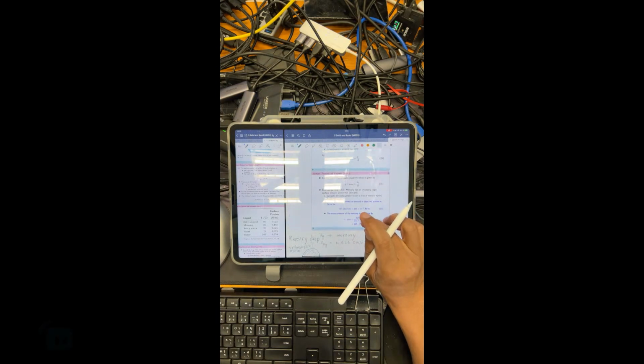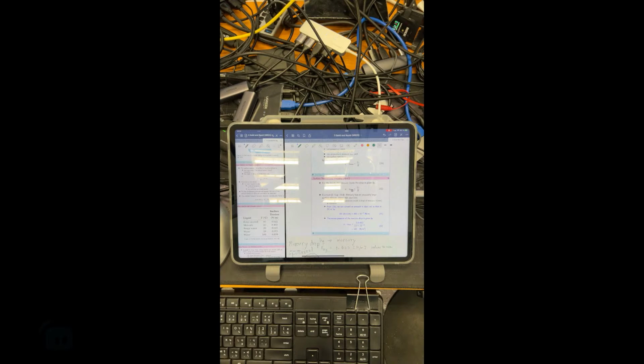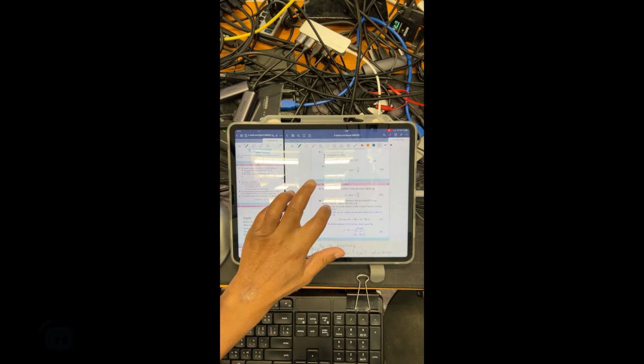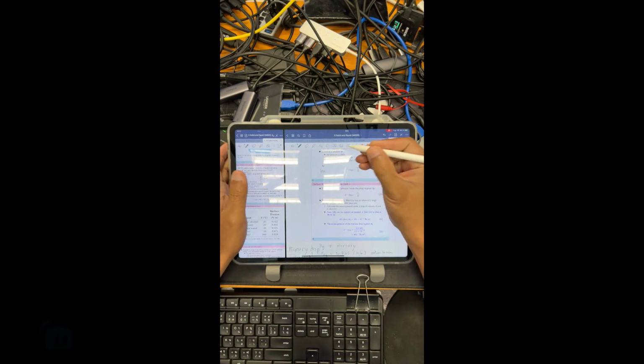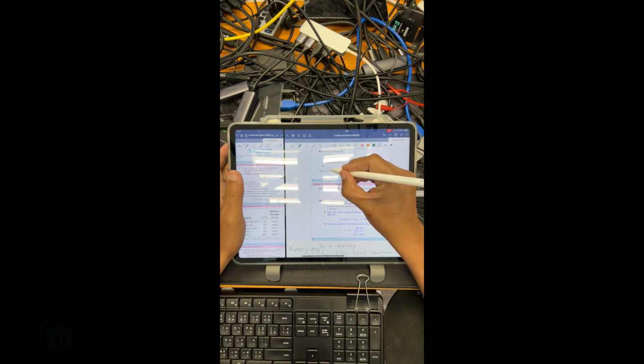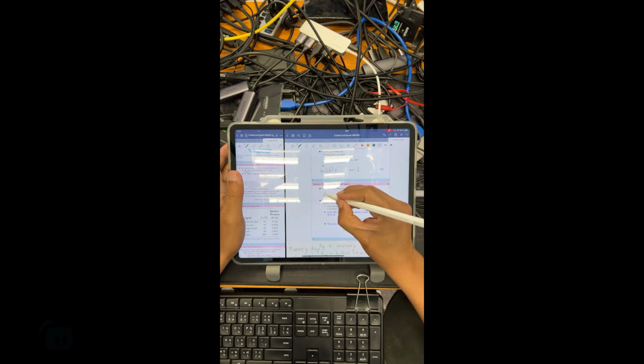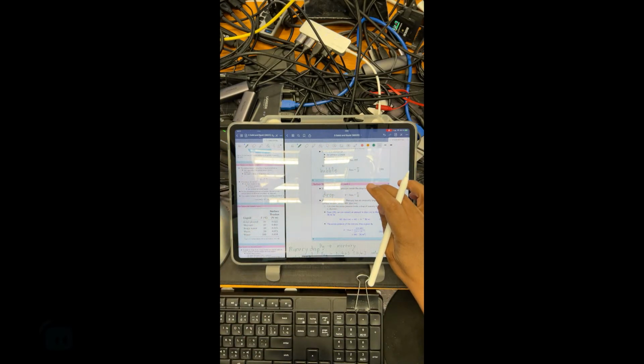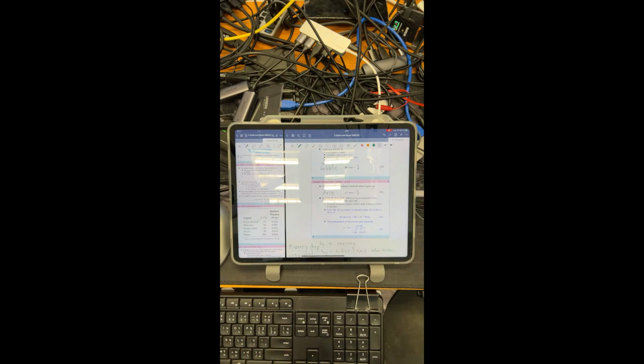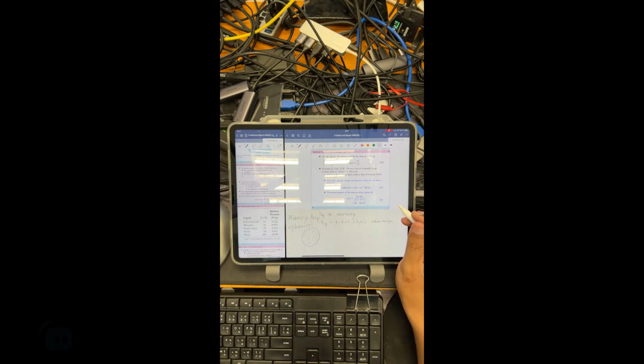Based on these, we have to apply this formula. We cannot use this formula because it is the formula for a bubble. Here is the formula for the drop, a fluid drop. It's different: a bubble has higher pressure excess, or pressure difference, inside, twice the value of the pressure excess in the drop. So we need to use equation number 30.